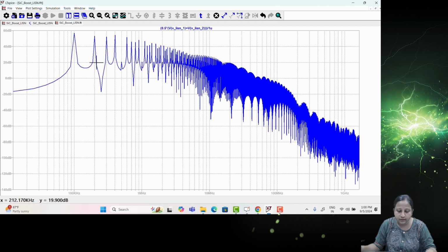See here, it is actually going a bit higher, like around 100 kilohertz. Initially, till before 100 kilohertz, the level is much less, but as it goes to higher frequency this level is increasing. So for lower frequency, this initial part was well below the standard limit. Here you probably have to design the CM filter, a filter for the conducted noise.